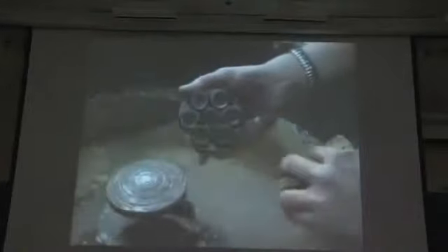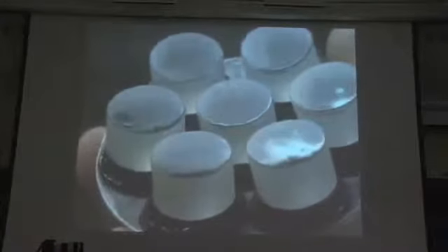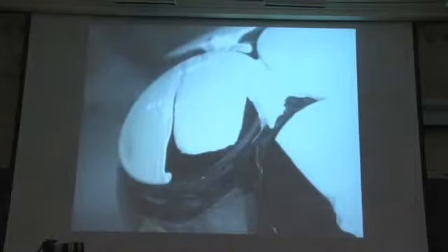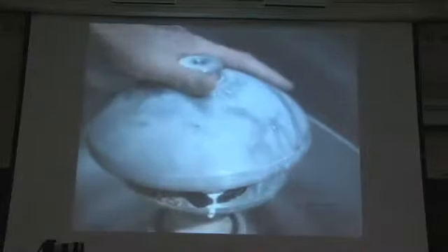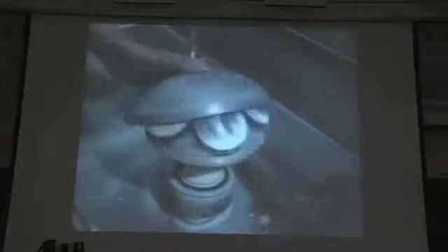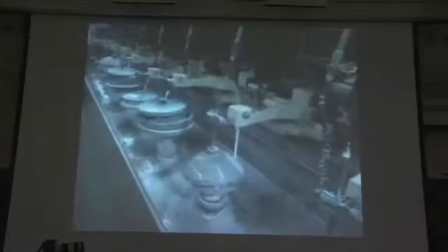The grinding makes the surface of the lenses uniform and smooth. They place a polisher on the lenses. It's lubricated with a very fine abrasive. For about an hour, the polisher oscillates while the block spins. Polishing makes the lenses smooth and transparent. It also gives them an even more curved profile.